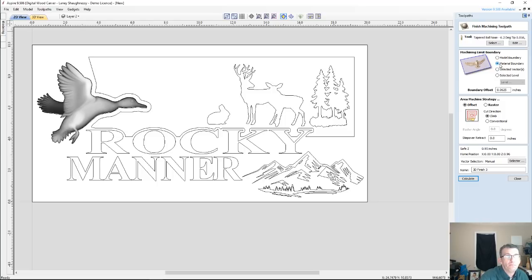This time I'm going to use the model as the boundary, because this is the only 3D part of the design. But I am going to be milling all of this material down to the bottom of that model. I'm going to be using a pocketing toolpath. But why have the 3D model cut do all of that stuff? So I'm going to use the model as a boundary, and I'm going to let it overlap, let it come off by 1/16 of an inch. I'm going to let my bit come past that model by that much, 1/16 of an inch. I'm going to calculate that 3D toolpath.